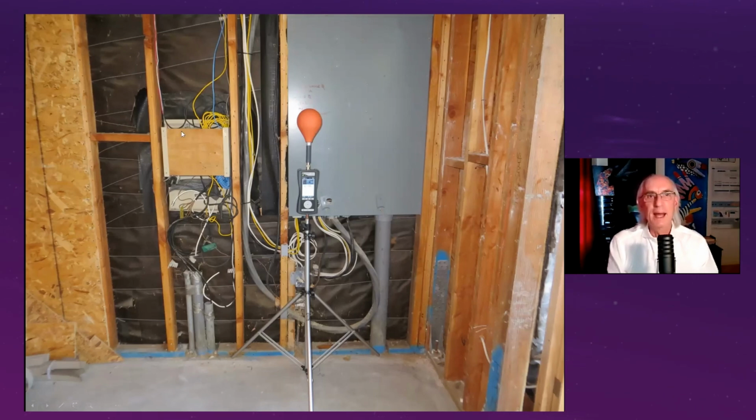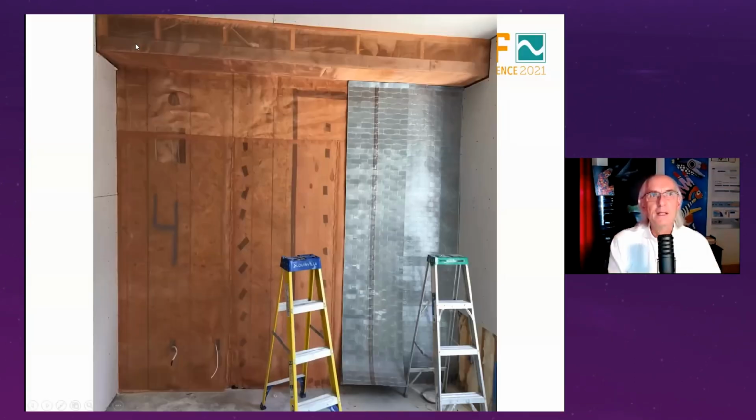However, the client said, try your best and try to eliminate the fields. So we have magnetic fields due to the current flow, but we have also electric fields due to all the wiring. So what we did is we used some copper wire mesh and covered this entire area to eliminate the electric fields. And then we used some special alloy material to put it over the circuit breaker panel and the main incoming lines to shield off the magnetic field. Result, very insufficient. We got about a 50% reduction.